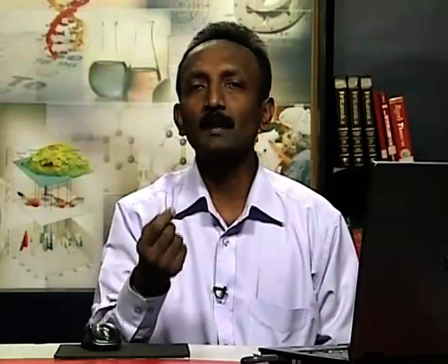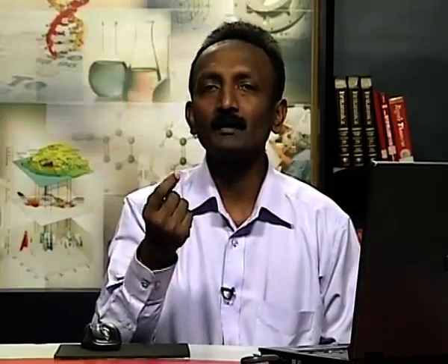The diameter of these vent holes will generally be maybe 2 mm, 3 mm or 4 mm. So there will be some vent pins, long, thin pins. Using these vent pins, we make vent holes. We insert it in the mold and take it out. Then a small hole of diameter maybe 3 mm or 2 mm is created. These holes will help the hot gases and vapor to escape from the mold.